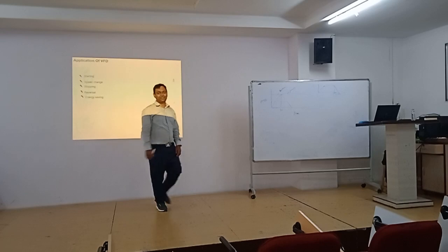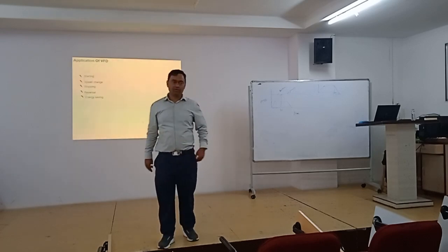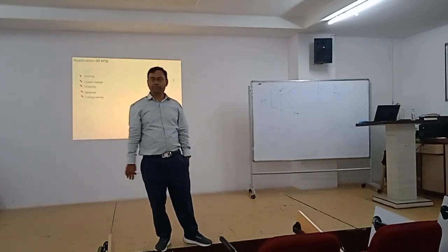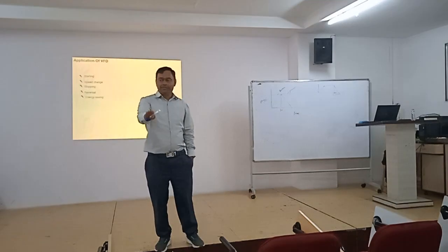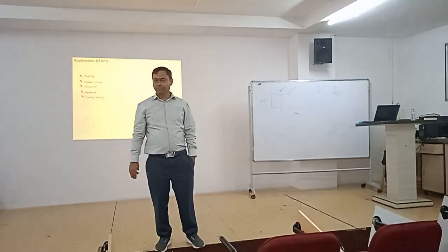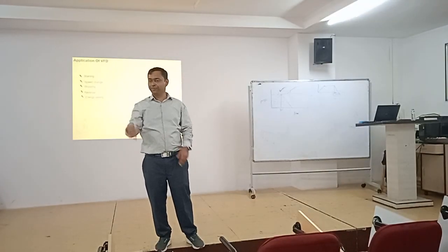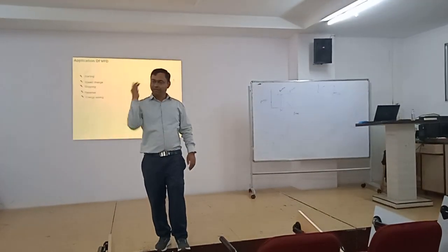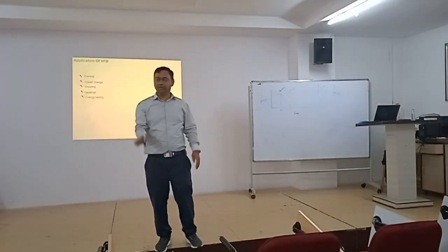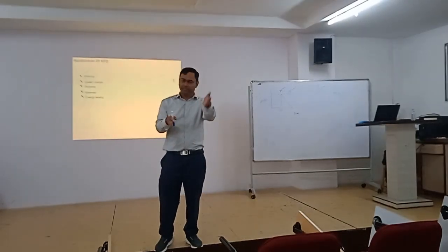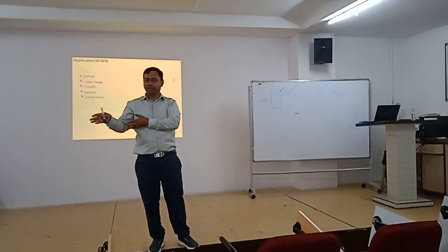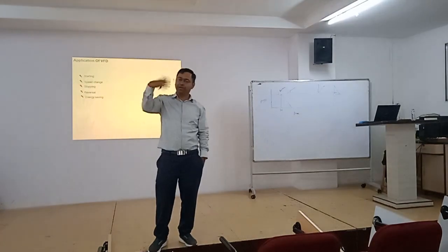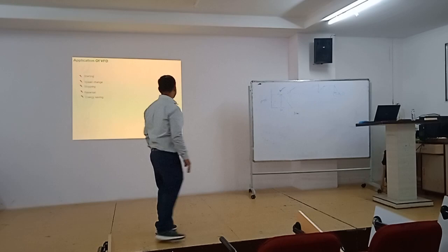reversal. If you do forward and reverse with an induction motor, how can you do it? You need to change the phase sequence. But now in automation, who will go and change the phase sequence? You delegate the work to the machine. So in a VFD, it will change internally. It will just change the firing of the IGBTs, change the phase sequence, and the motor will change direction. It's very easy in this.